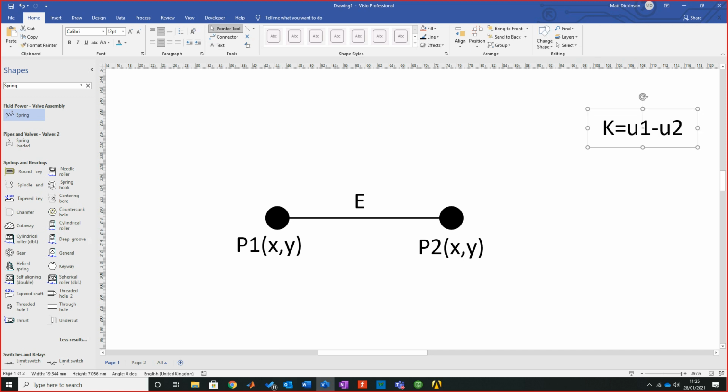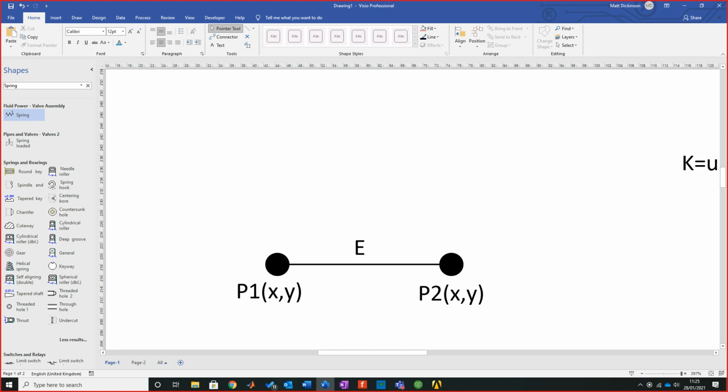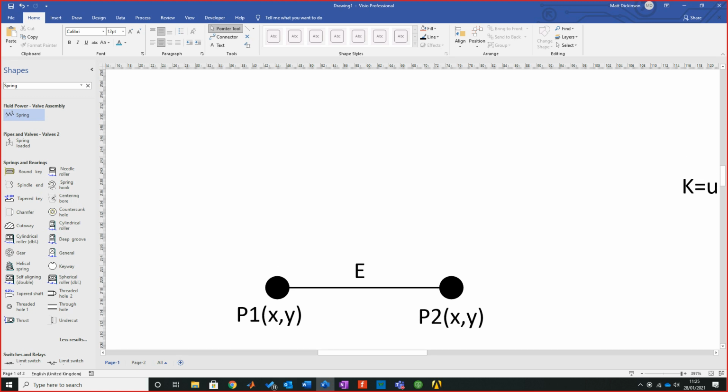With that in mind, it means that if we've got an original distance and a secondary distance, that's going to affect the K value. We've got a way to be able to pull the strain out. We've got a way to relate that back to the spring stiffness. We've got an overall way of understanding displacement and how these two nodes talk to each other. Now, I will get to a big point with this, so please don't think that I'm just stringing you along. Let's bring in another node, if I drop in another node.